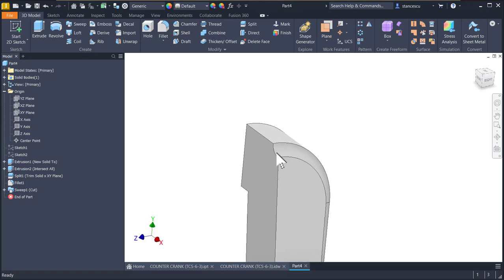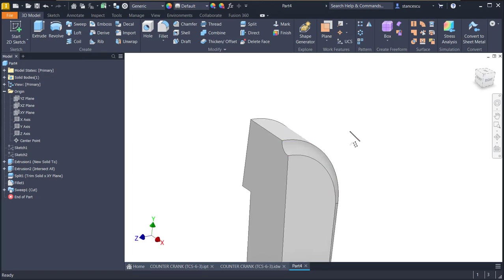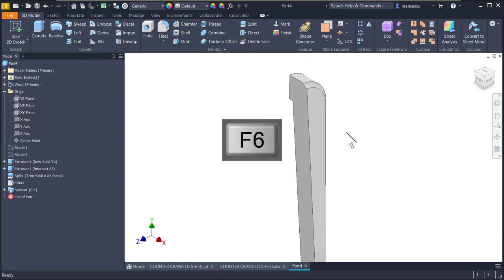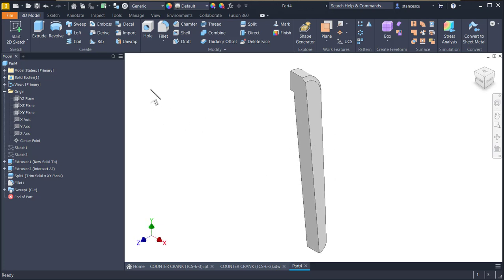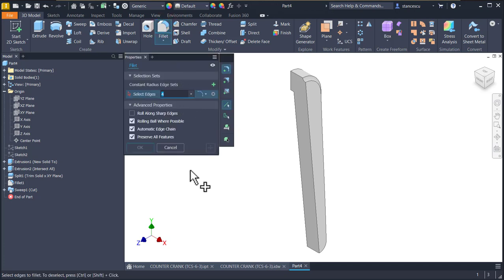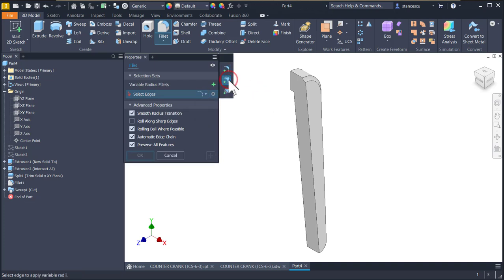with the inverted fillet here. I want to mention that if you take a look at my tutorial number 271, you will observe that we have an option of inverted fillet, but the problem is that we cannot combine that option with this variable radius fillets.